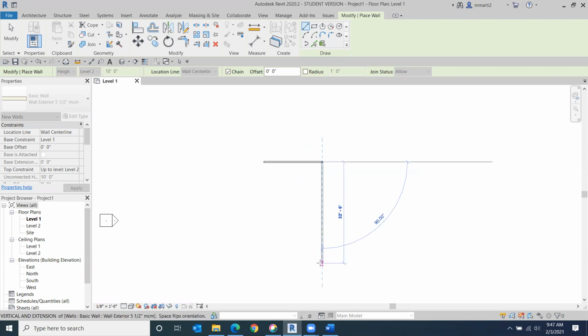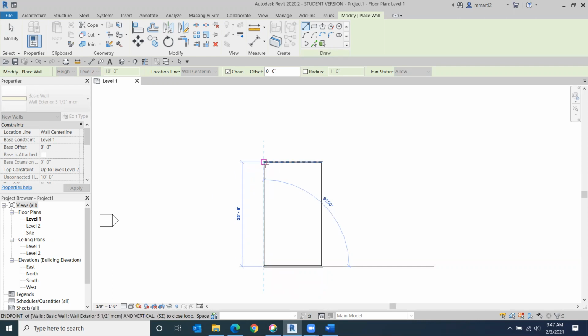Say this next wall right here that I'm going to draw is 32 feet 7 inches. Well, I'm going to get it close to that. Say just a shotgun house. It's just a rectangle. That location line is going to pop up, so that end of those two walls are now even. And I can click there and I can connect these guys up at this point.